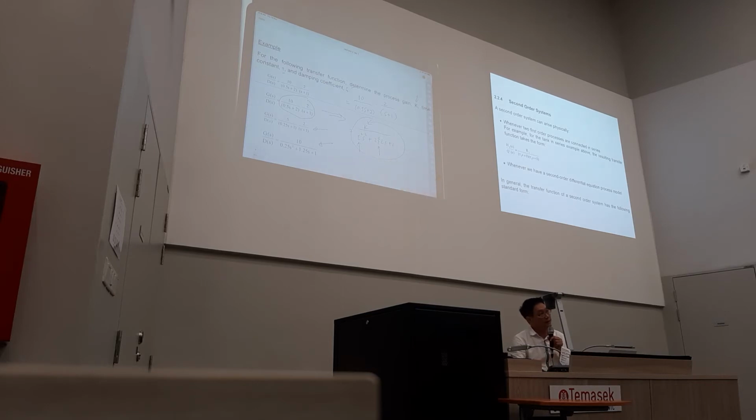So if I compare to the standard second order transfer function, the top one is k, and I know this one and this one represent here and here. Okay? So if I look at this one, what is my k value? 10, right? So k equals 10, so I solve the first parameter that I want for the second order. And what about 1.25 compared to here? I have 2 zeta tau equal to 1.25, right? So before I can solve for zeta, I must solve for tau first, right?